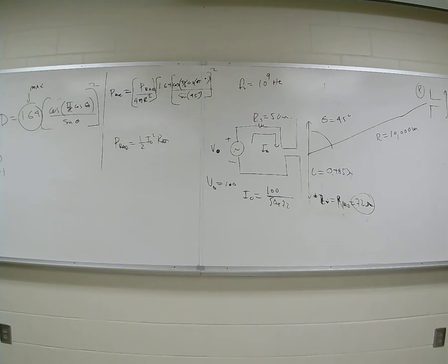0.0039 volts per meter. That's 3.9 millivolts per meter, which is reasonable. All right. What do you get for H, just out of curiosity? You know it's going to be that divided by about 120 pi, right? Kind of eyeball it. If you divide that by 1,000, you get about 0.1 times 10 to the negative 3. But you should have a few more significant digits.